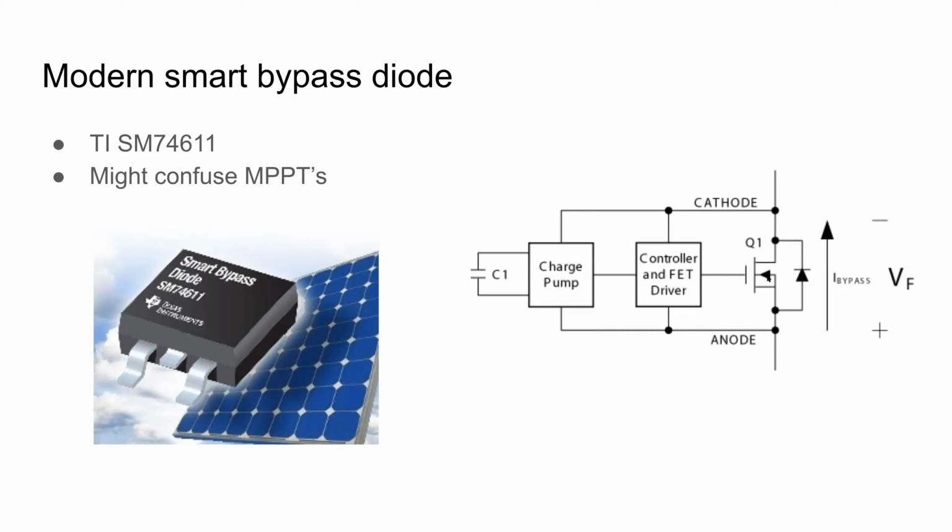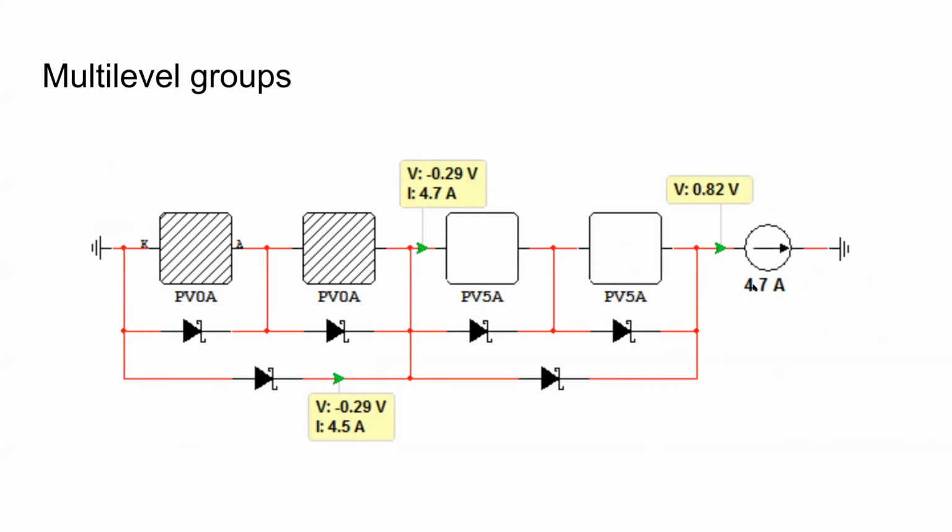And what also happens is that once you want the diode to turn off, sometimes the switch stays on while you don't want it. It just sometimes samples to see if it should be on or not. And that could confuse the tracking algorithm of the maximum power point tracker as well. So you have to be careful with that. In the datasheet, it usually mentions how often it looks to see if it should turn the switch on or off.